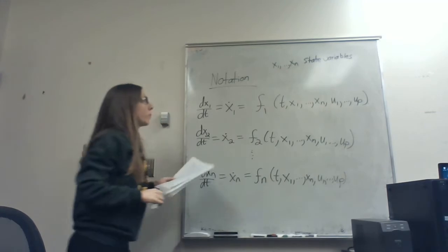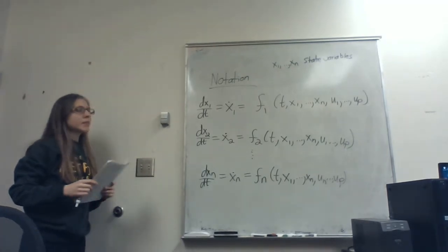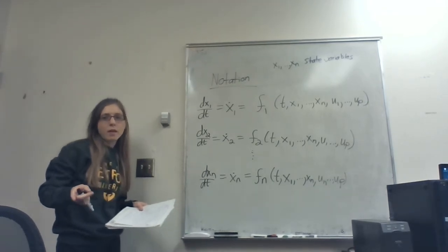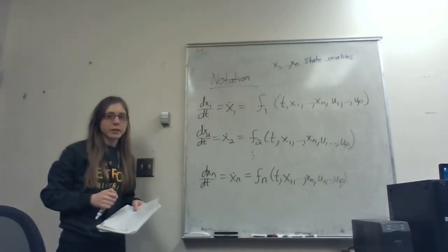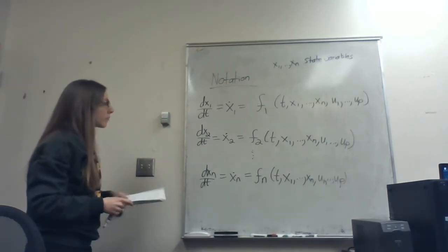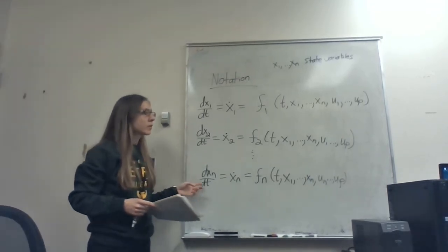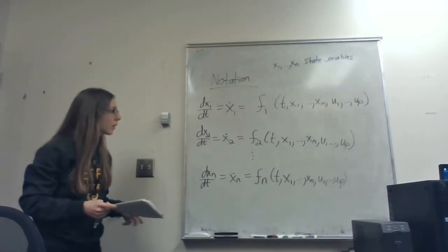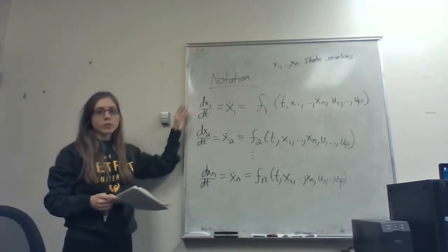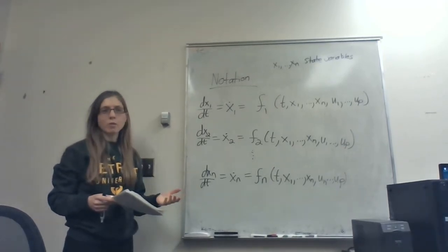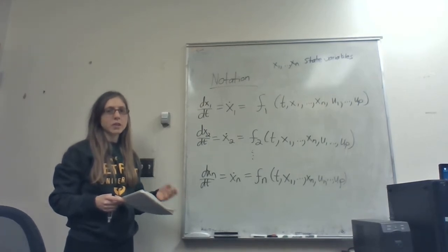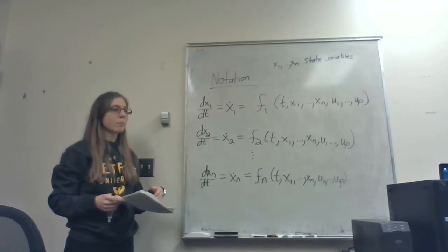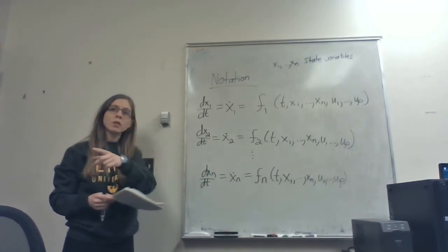Just to clarify this point, this is similar to the concept of outputs in the undergrad control class, but it's not exactly the same. When you have a system of nonlinear differential equations, outputs are what you measure, and you don't necessarily measure every state. Like if some of these are concentration, some are temperature, maybe I only measure the temperature, but that doesn't mean that the concentration is not evolving over time. So the concentration remains a state, but the temperature is both a state and an output. Does that sound good?